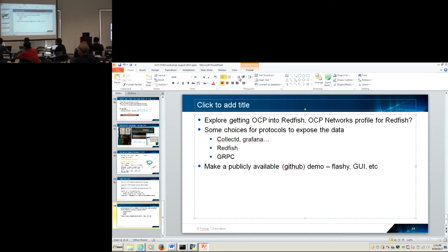So it's not fast. On the other hand, there's not much other traffic going on that bus. I mean, actually, each one is an isolated bus between the CPLD and the module. So each one is actually, they all have the same address. They're all at I2C address 50, or A0. So there's not a lot of traffic to that. But anyway, I don't think there's a problem with the system being bogged down, but there is a problem with just the amount of bandwidth available through those buses to get the data out of the system. So you can't monitor every tenth of a second.